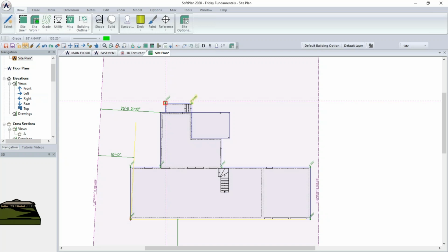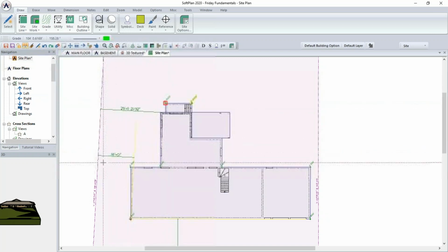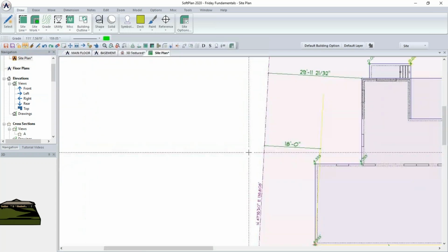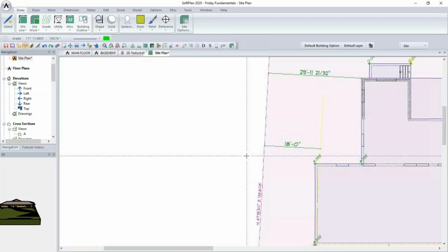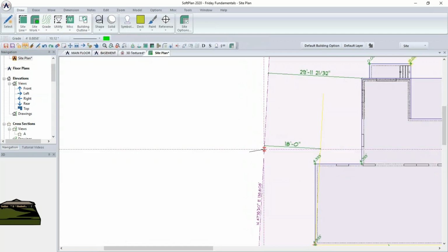The trick to adding grade lines, as well, with cursor snap on: the first thing is optional, but I like to start my grade line just beyond the outside edge of the property, but the next click should snap to the edge of your property. The number of clicks you then do next is also important. You can add as many as you want, keeping in mind that the more clicks you add, the greater change in the grade is going to occur.